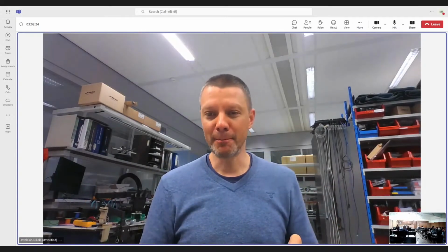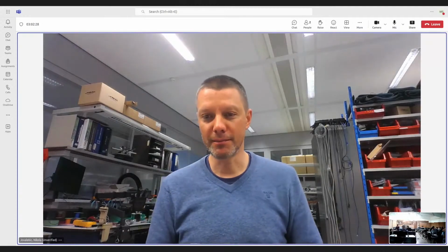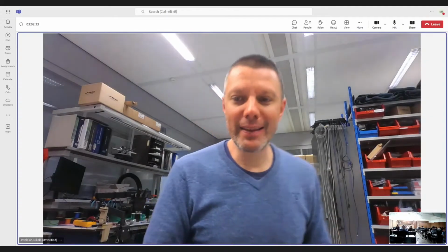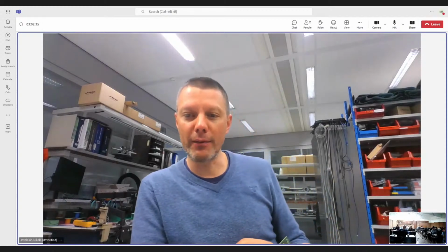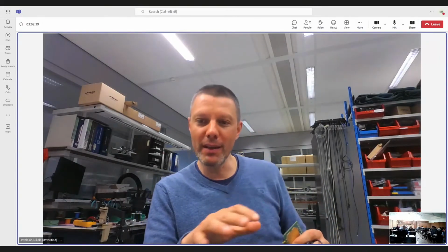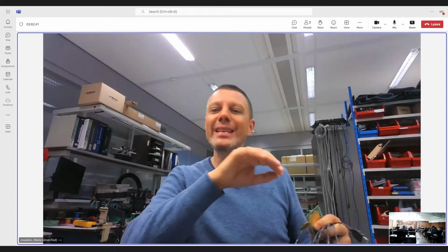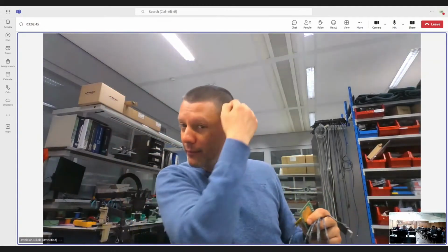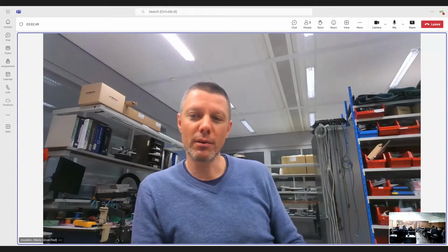We don't know anything. According to simulations, it should work. How do we do that? Well, we need a measurement device for that, which is called a TDR, time domain reflectometer, to see the impedance profile. Do you know what the differential impedance for USB 2.0 is by the standard?